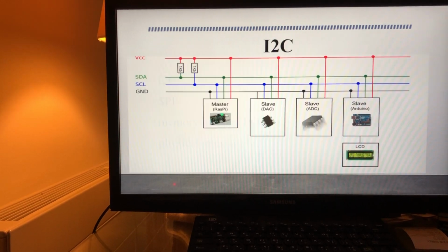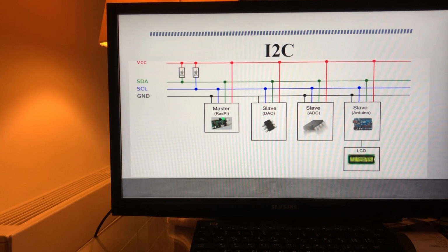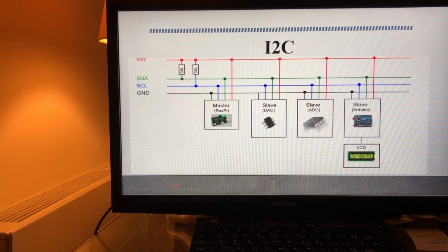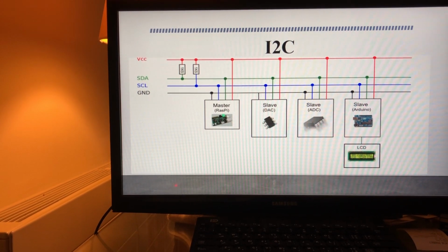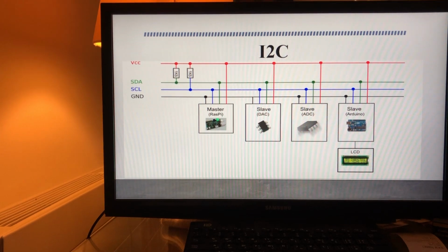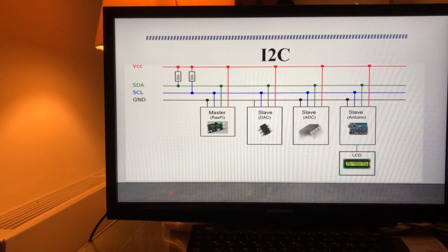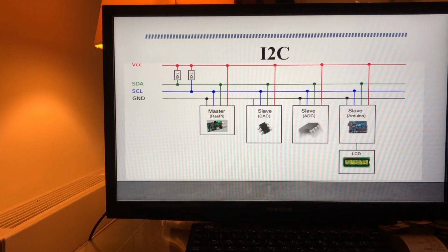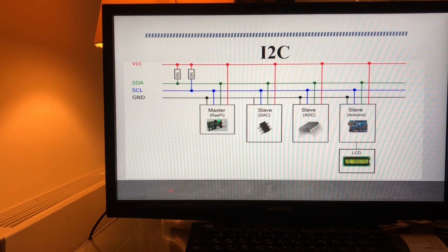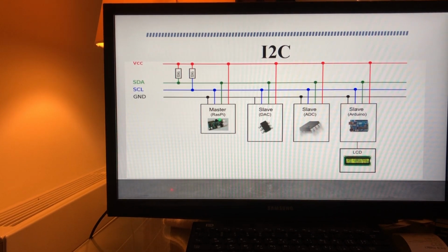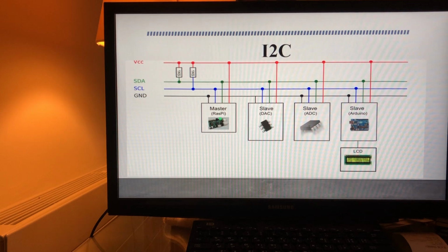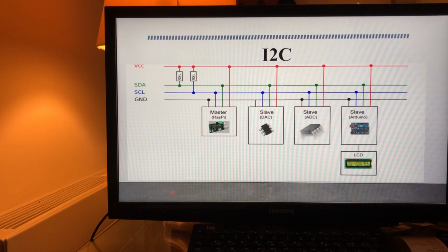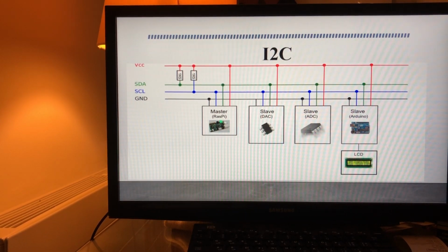Starting with I2C, the protocol is a centralized serial communication protocol that works with a clock and has two-way communication. SCK is the transfer clock pulse from the master device to the slave, and SDA is the data transfer line when writing from master to slave, and when reading from slave to master. That means it is a two-way transfer.